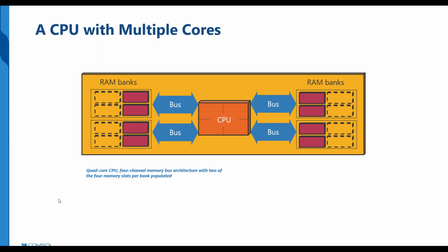I got the question on how discretization order affects the acoustics module and acoustics problems. It's a bit of a different question. Higher order for acoustics problems, wave problems, will normally affect the efficiency, but by just increasing the order, you will get a more coupled problem, which is more difficult to solve for.